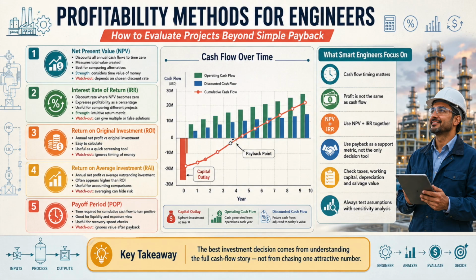For a decision-grade analysis, build the evaluation in layers. First, establish the technical basis: capacity, production profile, availability, efficiency, operating life, and expansion requirements. Second, establish the investment basis: fixed capital, owner's costs, land, working capital, startup, pre-production costs, and later capital additions.